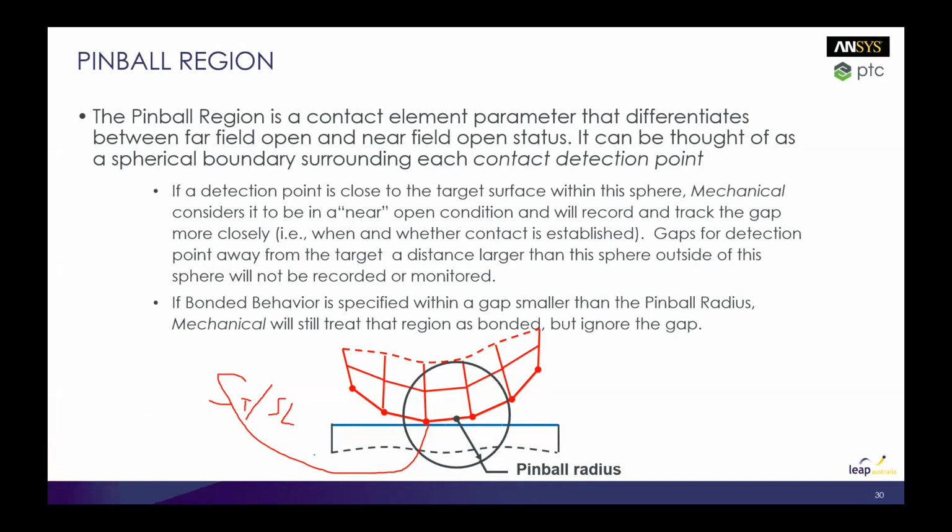Okay, so anywhere where we've got a gap and it's in the pinball region, this is classed as what we call near contact. So this would be open. Anywhere that's outside the pinball is what we call far contact.